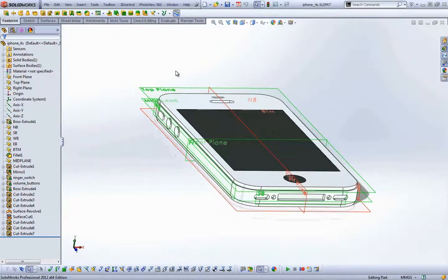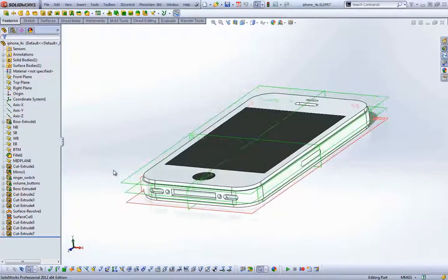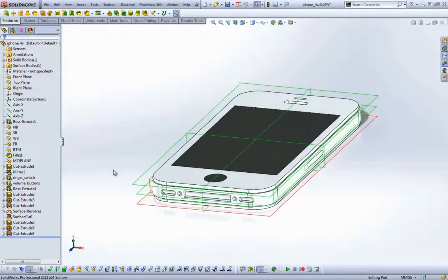For a skeleton that's expected to change a lot, especially a base part that's expected to change a lot, you're probably better off building right in this part to use it as a skeleton. Just right where the insert bar, or rollback bar, is here, just start building your skeleton right on top of the features that are already here.